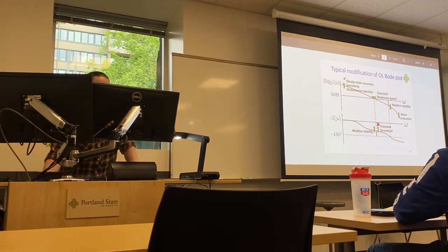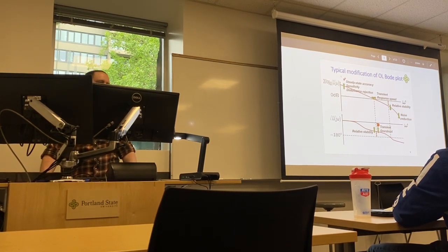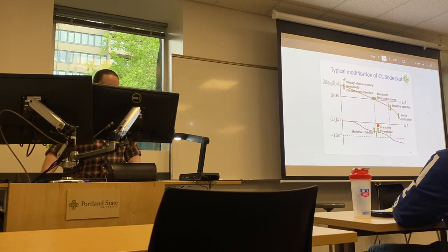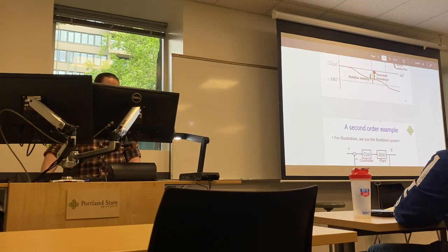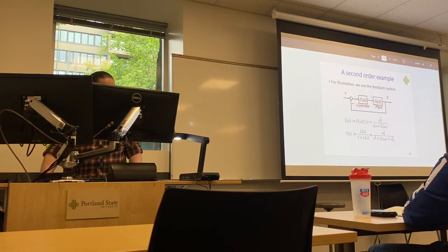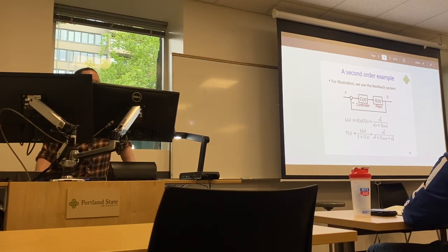Okay, so we've checked off generally what we're looking for with steady state accuracy, which is we want our gain to be high for low frequencies. Now we're going to look at the transient overshoot, and this applies more to the phase area over here. So if we're looking at this, again, same illustration here, we have a controller and plant with no sensor.